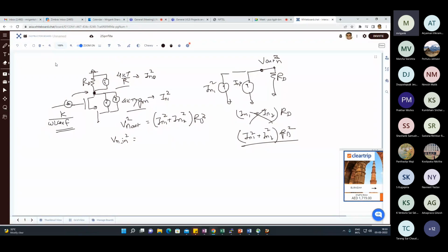Here we have seen the effect of device parameters. If you increase W by L or increase the bias current, the Gm changes, and if the Gm improves, the overall input referred noise improves. We have discussed the reason for that also: even in the active load case, the Gm of the input device helps in reducing the overall noise contribution, because the Gm of the input device is responsible for magnifying the signal also, whereas the Gm of the load device is not magnifying the signal.